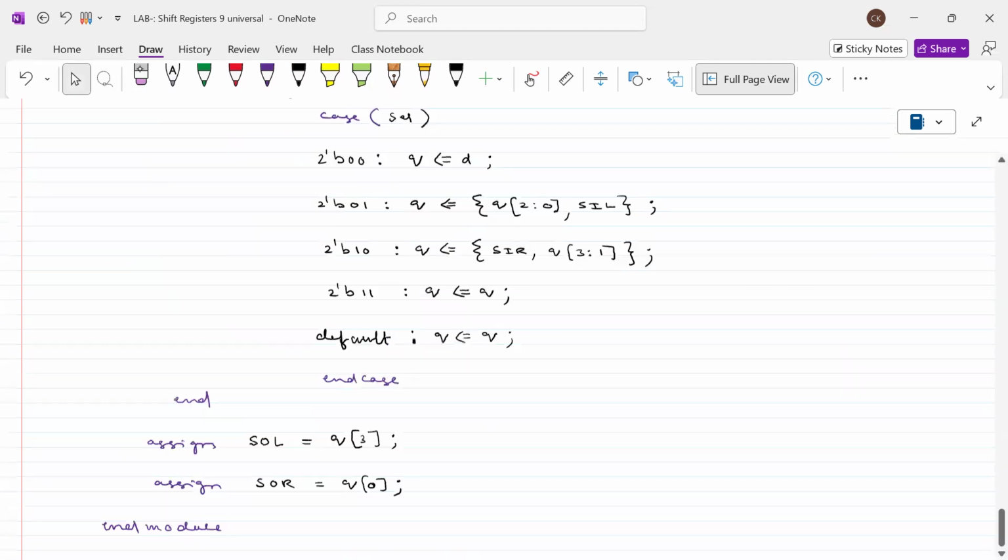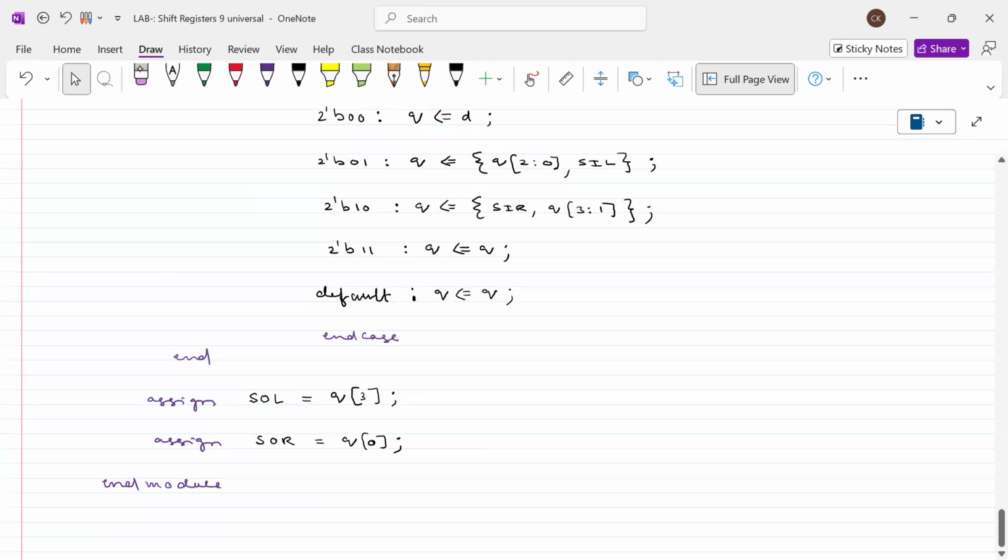Suppose here I'm using blocking statements. Therefore, definitely when we talk about the assignment statements, we have to type by using the blocking statement. Whereas in the always statement, for the modeling of sequential circuits, sequential assignments, we go for non-blocking assignments. This reason I have told you previously also.